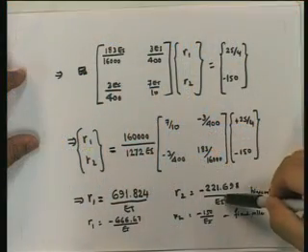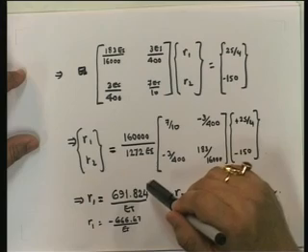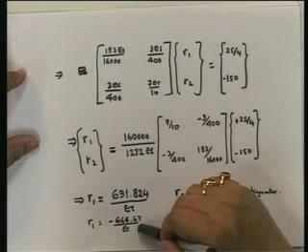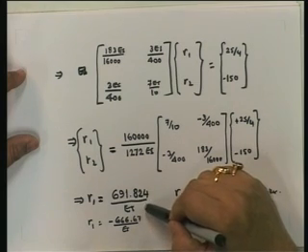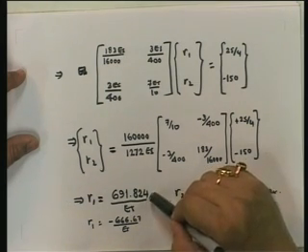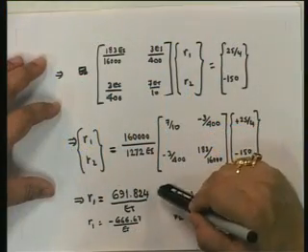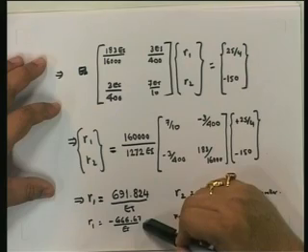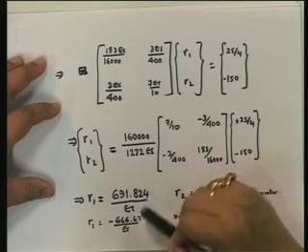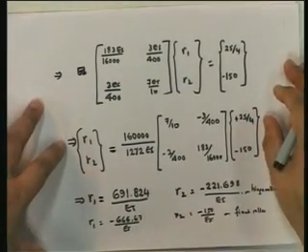Look at the rotation. The rotation has gone up significantly, and more interestingly, R1 was downwards when it was fixed. Now that you remove the restraint, it's actually upwards. Isn't it very interesting what kind of an effect this has? You would think, what have I done? I have just taken a support and removed the rotational restraint. But the whole displacement pattern has changed: now the support at C, instead of moving down, is actually moving up, and the value is much larger.